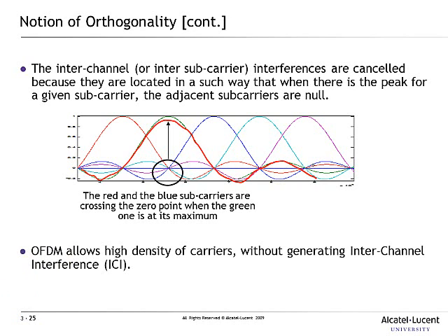So I'm taking one of these sinc functions and placing it here, and I'm adjusting so that the second sinc function is sitting somewhere here. But what you'll notice is at the point where this sinc function has a maximum value, all other sinc functions have a zero value. They all pass through that point, so they don't interfere.